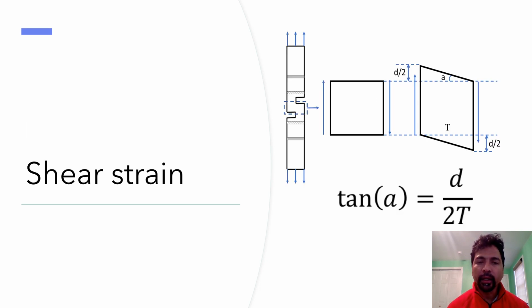This standard doesn't provide a shear strain expression. Hence, we have a schematic here that shows how we measure the shear strain for the shear stress-shear strain diagrams, which we wanted to plot. I will be discussing those in the coming slides. Now, we took a point in the shear zone, and this point can be represented with a small square, which is under shear deformation. When shear deformation happens, the square becomes a kind of rhombus. Now, we measure the change in angle there with the help of the expression given there.